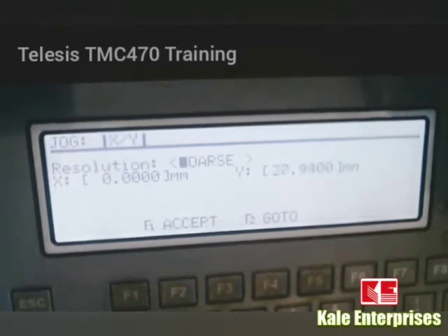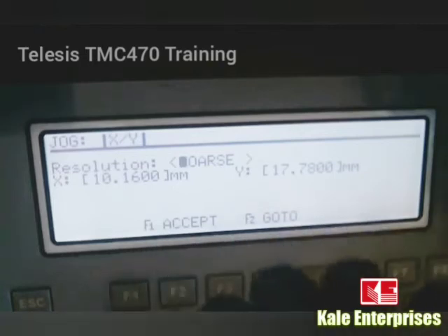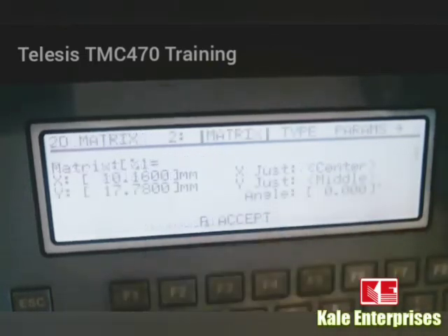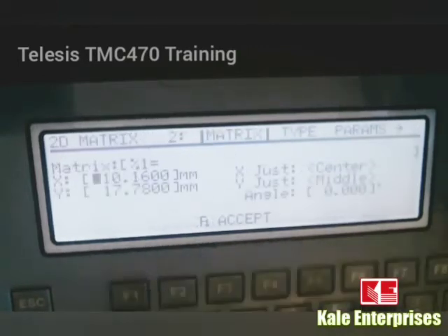And you can say, hey, you know what, I want this piece to be 10.117.7. Again, the way you hit the jog is on the keyboard in the bottom right, there's a key that's got 4 arrows. When you hit that, you go to this screen called jog, accept. You just called out a point of 10.117.7, and I want to make this my center middle point.